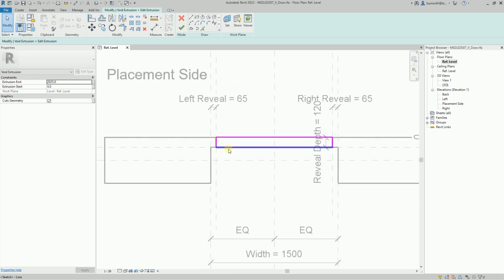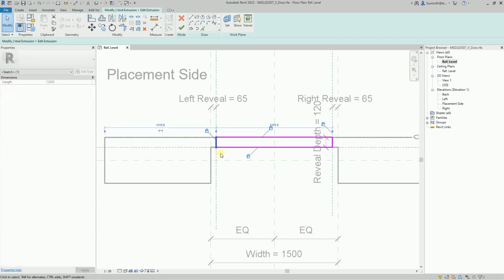When you change the reveal depth parameter value, the corresponding reference plane moves. Follow it by a sketch line. In the case when the reveal depth is 0, these sketch lines coincide with each other. The lines that define the side faces of the extrusion element will turn to points, and the object itself will be flattened. This is what will cause the error.